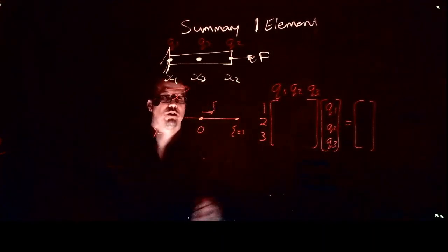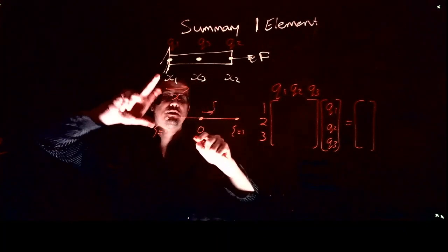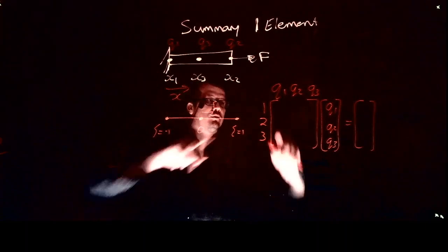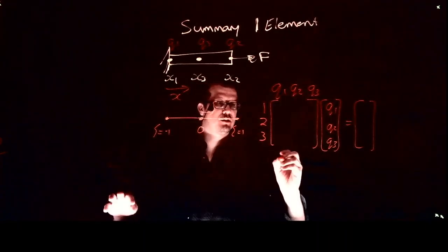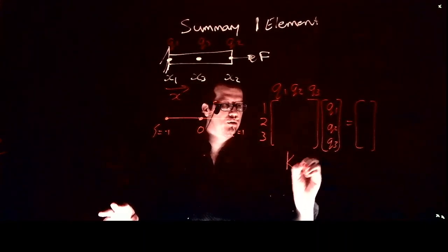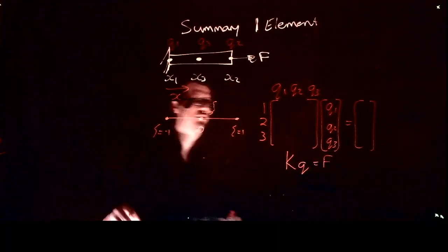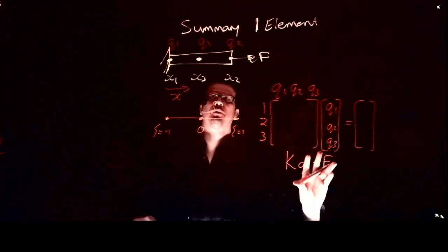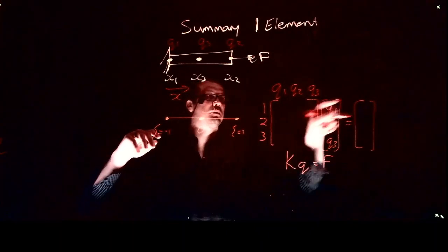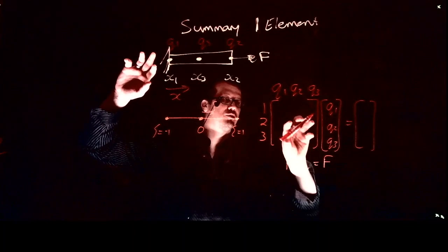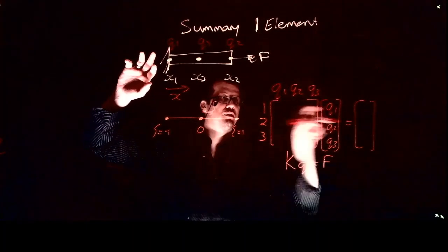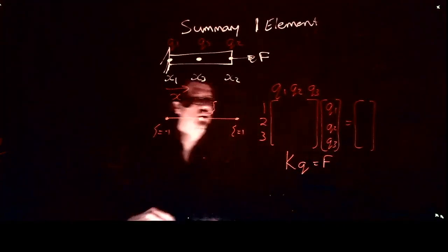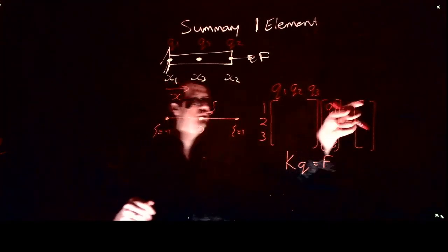Okay. So what we could do is map x and psi using isoparametric formulation, set up all the information to set up our stiffness matrix, and this is typically called KQ equals F. Okay, that's essentially where we were. Then once we've done this, we could eliminate the displacements that were known, like Q1 for instance, and have the reduced system. We moved this Q1 multiplied by this across to the other side, solve for Q2 and Q3, and then in the end solve for the reactions at Q1.